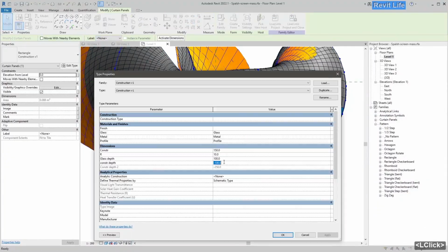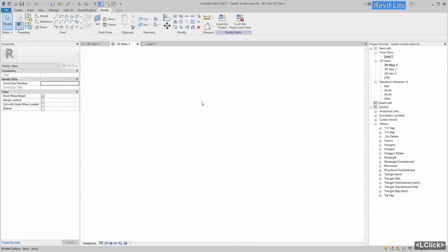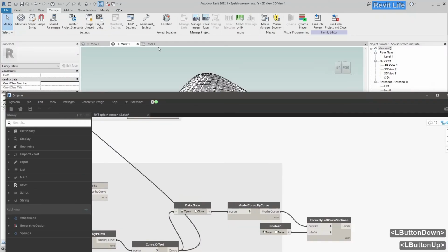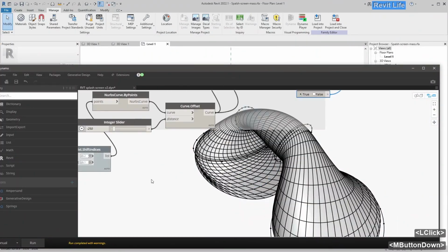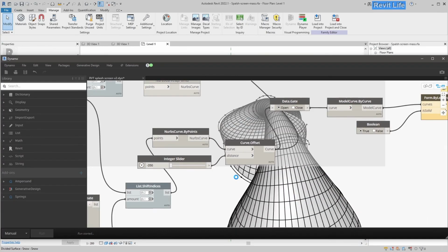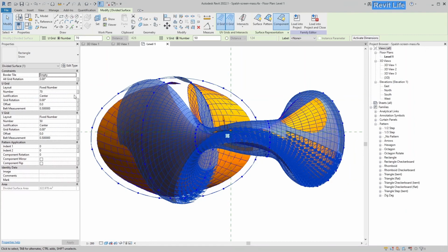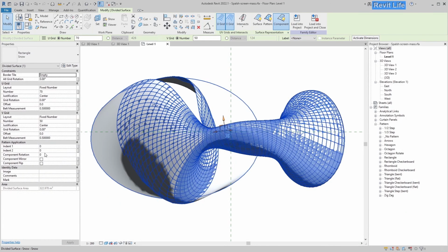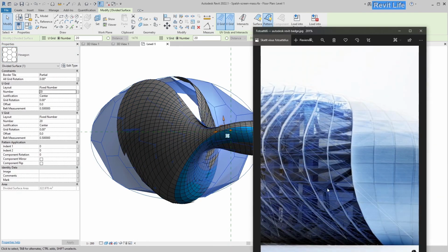At first I tried to offset the surface onto the inside, but that wasn't successful because I couldn't export the surface to the Revit. The next idea was just to make the surface exactly the same size as the previous surface, but with a much simpler grid division and surface rotation. So I exported that surface and divided that surface, and I added octagon pattern to that surface. And here you can see the octagon pattern.